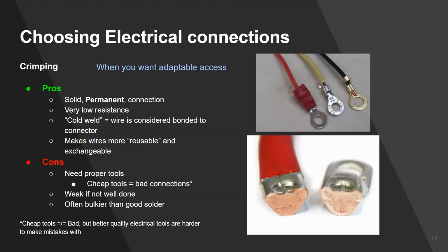So this is what it looks like when you keep the sleeve. So that plastic coating, when it stays on, this is what it should look like. And then you could put heat shrink over it if you want, but you don't necessarily need to. If this plastic thing gets removed for whatever reason, this is what you end up with. This little metal piece that gets bent around your wires so that it creates a very, very tight fit. And it's so gripped onto those copper wires that they've bonded into place. So it's considered a cold weld for that reason.